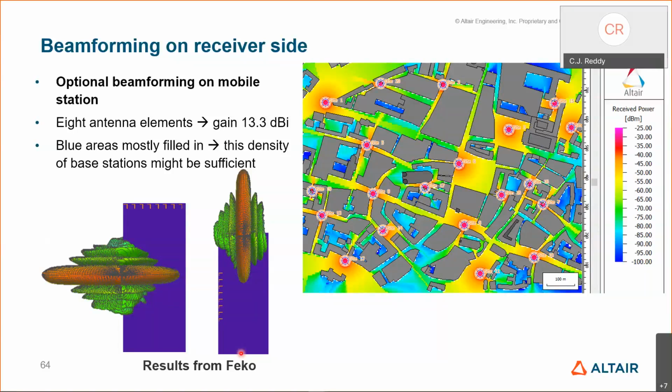So if you do that, based on those mode behaviors, you are now able to understand the physics behind the structure. In the past, what people have done is that they arbitrarily use optimization or excitations. By intuition, they say, okay, this shape could support something like this. Let's put something there and put some slots and do brute force simulations to find out what it can do. Now, before you do that, if you can do characteristic mode analysis and understand the electromagnetic behavior of the structure, you may be able to come up with a better and more efficient design in a shorter time than doing it the brute force way.